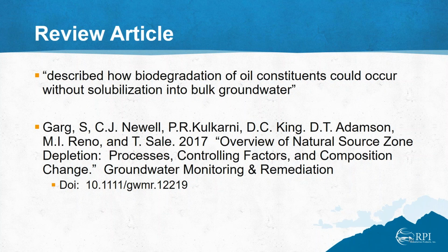Then as the oxygen is consumed, it trends down into an anaerobic state. And the game is being played inside the porous structure of the carbon. It's not being played out in the formation at large. So as that changes, we now need organisms that can take advantage of the anaerobic condition. So the blend of organisms that we use and inoculate the BOS200 slurries with have organisms that can take advantage of those different conditions.